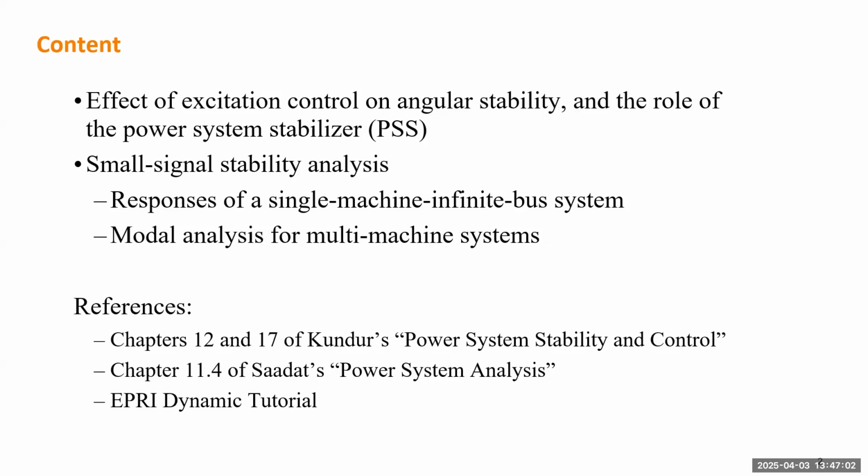I had the experience in some presentations. They talk about using the solar farm to help improve the damping of oscillation, and they directly borrow the power system stabilizer there. But first you need to understand why we need the power system stabilizer. It's not like a unified controller which always gives you positive damping. You have to utilize it correctly. The power system stabilizer is designed in such a way because they try to compensate some effect from exciters. That's what we're going to talk about.